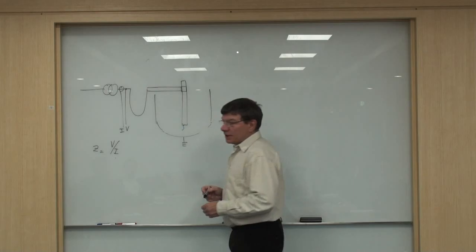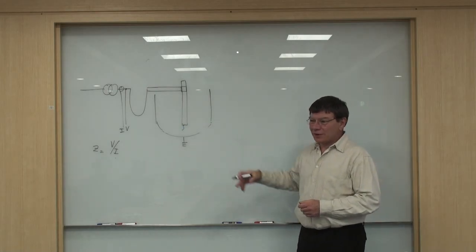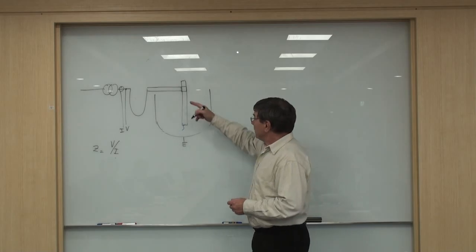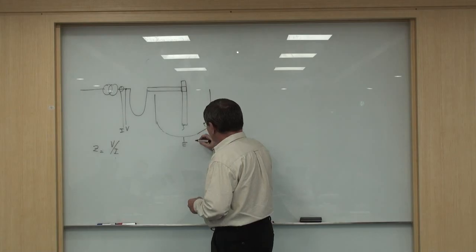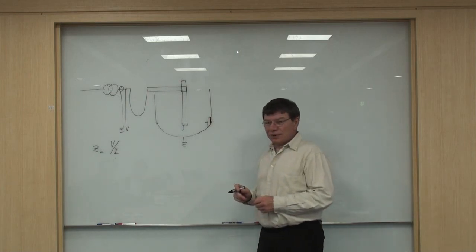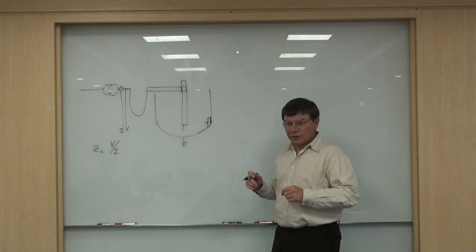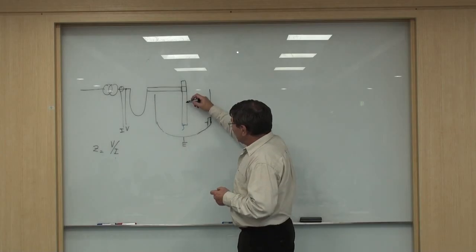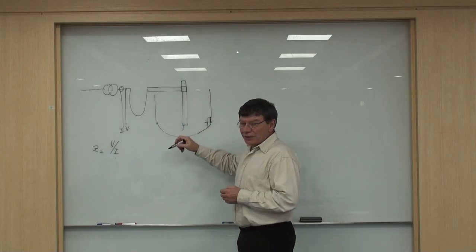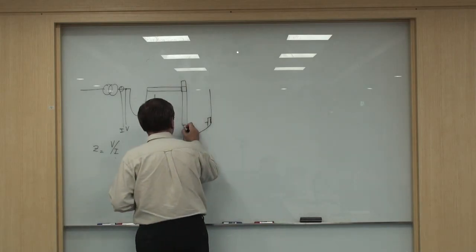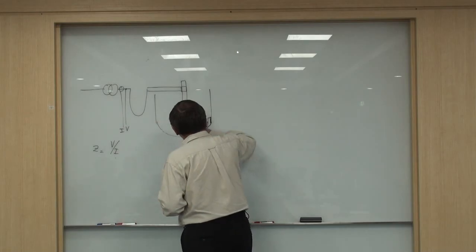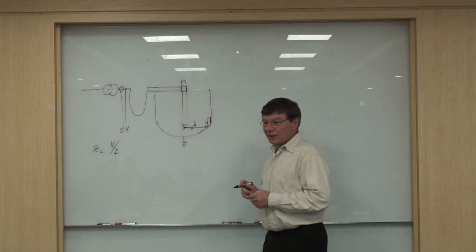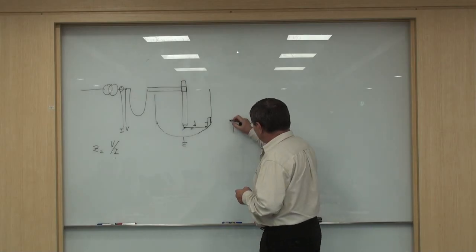In fact, he made a statistical study comparing several furnaces using different voltages and different currents. And he established that the refractory index, that means the speed with which the refractory was worn out, depended on the voltage, on the current, and on the distance between the arc and the refractory. This is the distance. So he established a magic formula.